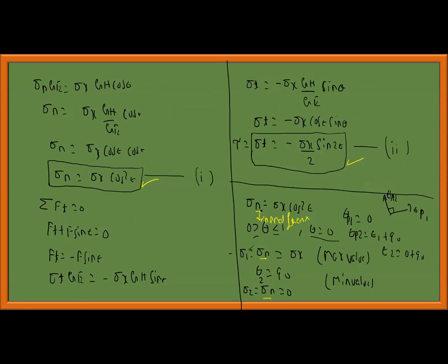By inspection, since it's a simple problem, I found the planes. I find the planes and then substitute these values, theta p1 and theta p2, into sigma normal to get the normal stresses. Okay, this is the first step.